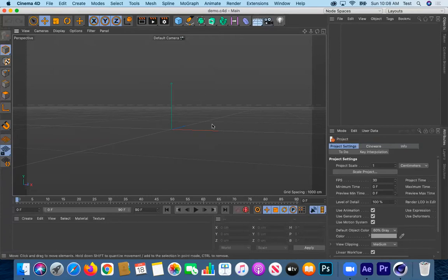Okay, so there are some shortcuts for activating these functions here, the pan, the zoom, and the toggle. That would be 1 on your keyboard for pan, 2 for zoom, and 3 for toggle. You see here in the center, I have this little indicator of the axes orientation. So again, Y is green, this is standard, X is red, and Z is blue. And the way that the arrow is pointing is in the positive direction of all of those axes. Here is the center of our scene. This is the origin of the scene.